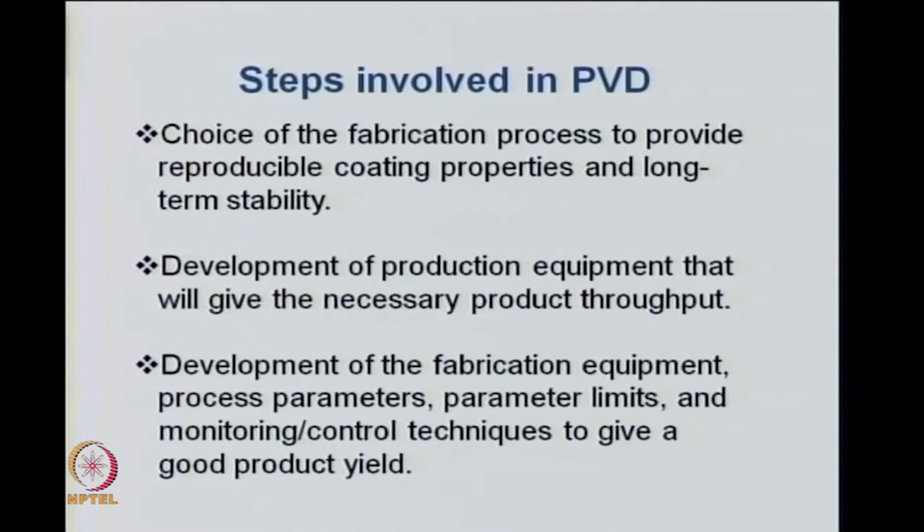What material you are going to use to coat the substrate is very important to know, because that will enable you to choose the proper fabrication process. Then you need to develop the equipment, that is the chamber in which vacuum has to be generated or the arc has to be generated, and if you need flow of gases, and how the substrate can be rotated or the substrate heater has to be placed.